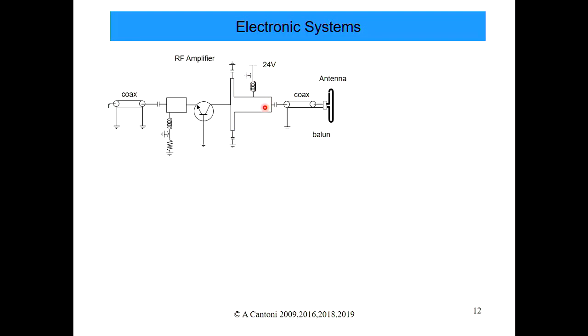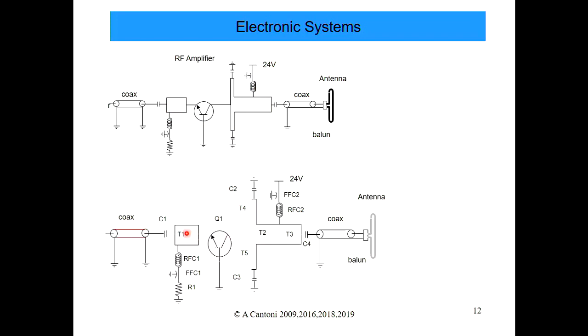When you actually make a printed circuit board, you often have one plane of the board that is ground, and on top of that you have wire traces. The wire traces with respect to the ground make a transmission line. And in these high frequency RF circuits, you can use sections of different size traces to produce transmission lines of different characteristic impedances and with different lengths. In fact, they can act as transformers, a bit like an inductor or capacitor or something in between.